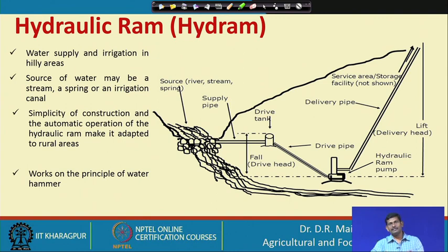There is a receding wave, so it creates an impulse that goes backwards. That sudden impact is called hammering. We are creating a hammering force on the water flow, and that creates a ripple, and that ripple force we can use to lift the water.